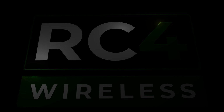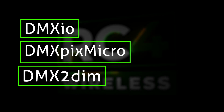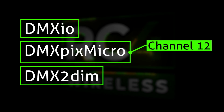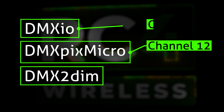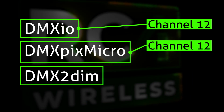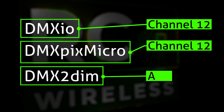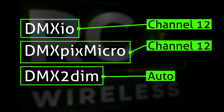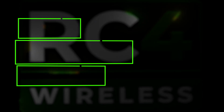For today's demonstration, we're going to use the DMX-IO transceiver, a DMX-PIX Micro XB, and a DMX2 DIMM. In our scenario, we want our DMX-PIX Micro XB to be set to channel 12 and not do automatic channel selection. And in order for it to connect to the DMX-IO transceiver, that also needs to be set for channel 12, not doing automatic channel selection. The great thing is, for every other device connected to this DMX-IO, we can just leave automatic channel selection on and it will automatically find it. So my DMX2 DIMM, I'll just leave automatic channel selection on and it will find the DMX-IO on channel 12.